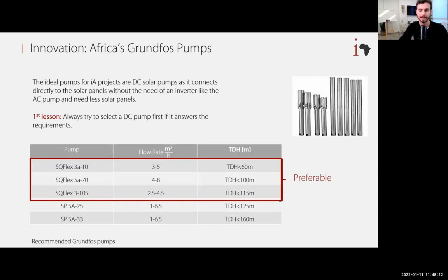Just like Sivan said, here we made your life easier, and we made you a list of the pumps we prefer to use. We would rather use DC solar pumps. This is the first lesson: always try to select a DC pump first if it meets the requirements.